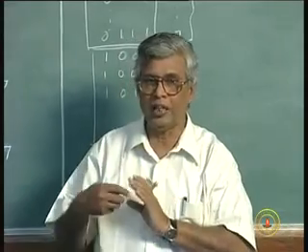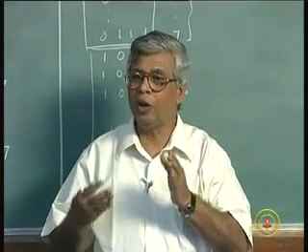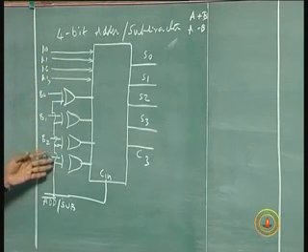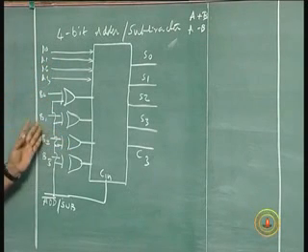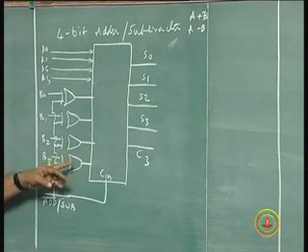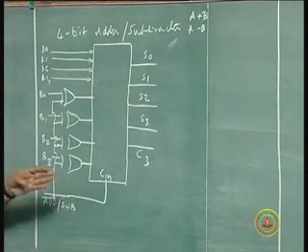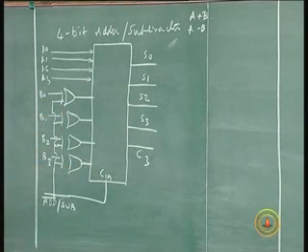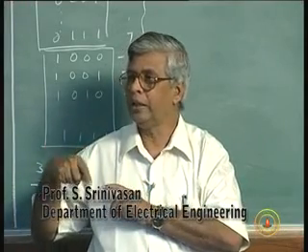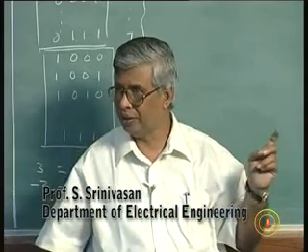And if you want to get the original number, we don't really need it, because we wanted 2's complement representation. We were given the number, we represented it and made a subtraction. The number was complemented, and we subtracted it, adding an extra 1. If you want to get the original number back in positive form, whether the result is positive or negative, you want the magnitude only, what I should do is a 2's complement one more time at the output, correct?